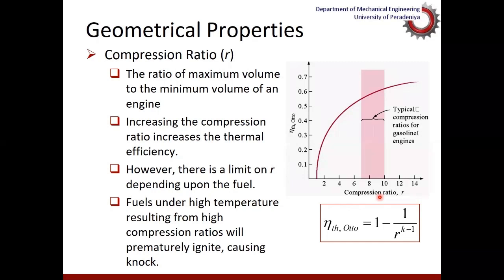Now, as you can see here in this curve, when you increase the ratio, that means if you reduce the clearance volume and increase the displaced volume, then of course you will be able to increase the compression ratio. Then you can increase the thermal efficiency.